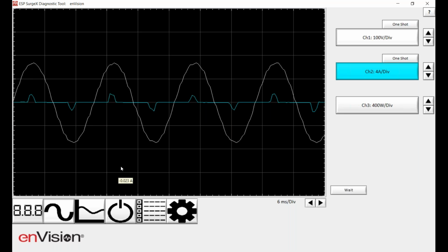You could install a larger circuit, like a 30 amp service or a 30 amp whip, then you can split it off to power all your small gear. If none of those are practical, in some cases you could consider adding a UPS or voltage regulator to regenerate the sine wave, if all the power ratings will work with your equipment. Yeah, I think that's pretty much it.